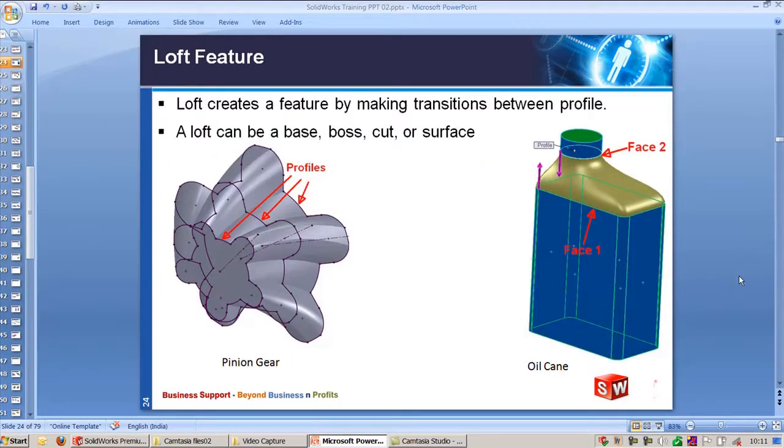Loft feature. Loft feature is created by blending different sections located at different distances. This geometry can be created by guiding the sections when they are blended at different levels. And also you will input a center line parameter, which we call a spine, which will support the creation of the loft feature. Let's see this loft feature in SolidWorks, and these two images will give you an example for creating the geometry using the loft feature command.